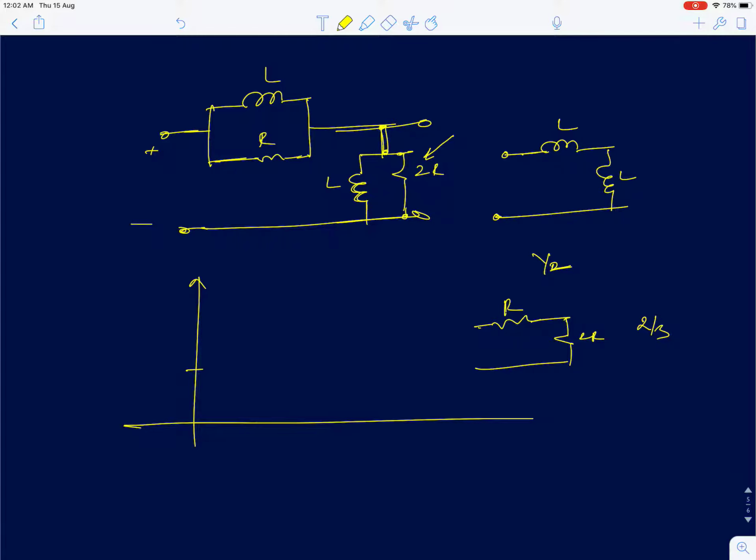So now on a frequency response graph, if you draw the half, the DC gain, and then the high frequency gain, it is actually greater than the DC gain. Now to reach from the DC gain to this high frequency gain, you have to first encounter a 0. It won't happen if you encounter a pole first. You have to first encounter a 0 and then the gain has to rise, and then you encounter a pole. So from that we can say you are going to have 1 zero and 1 pole.